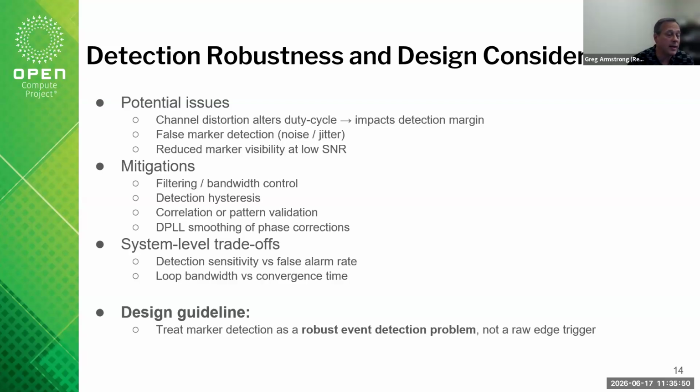So you have all these things that you can take advantage of because of the physical clock, as opposed to relying on a 1 hertz signal only to maybe only detect what happened a second ago, right? It's always going to be like what happened as opposed to what is happening. That's the advantage of the multi edges that you get with the 10 megahertz. And as I talked about, there's a lot of mitigation controls you can do now. You can do filtering through bandwidth control.